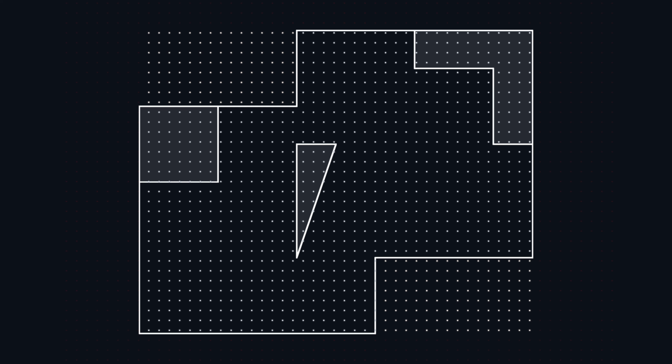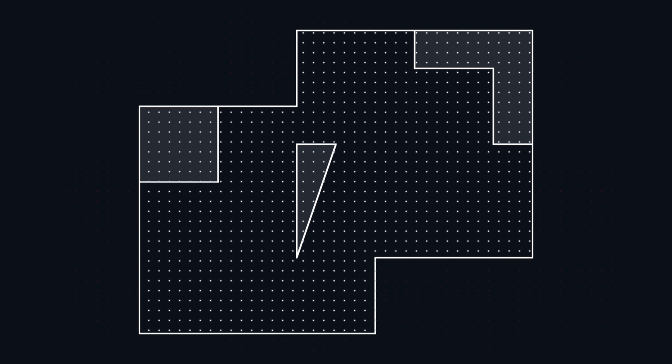Now, if we take our set of vertices and the polygon representing the room, we can easily determine for each point whether it is part of the polygon. If it is, we keep the point, otherwise we throw it away. But our room also has obstacles that the robot can't pass through. So it doesn't make sense to keep vertices inside them. We can use our algorithm again, but this time we discard a point if it belongs to a polygon representing an obstacle, and we keep it otherwise.